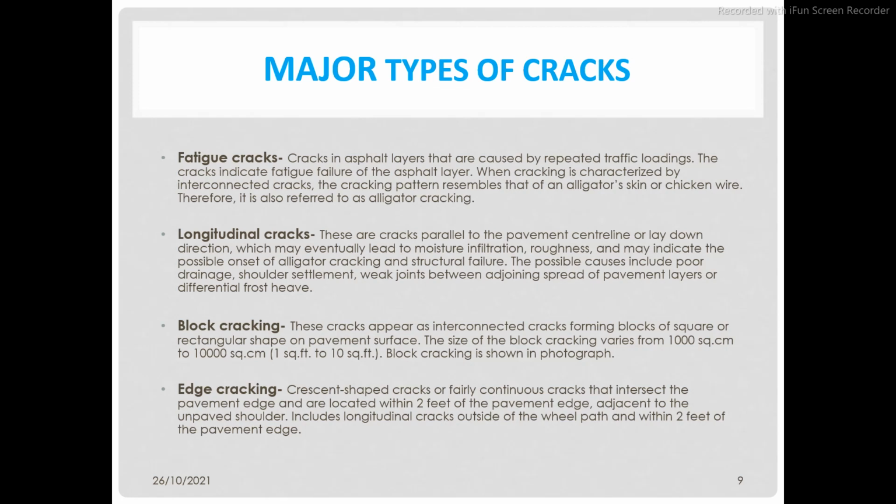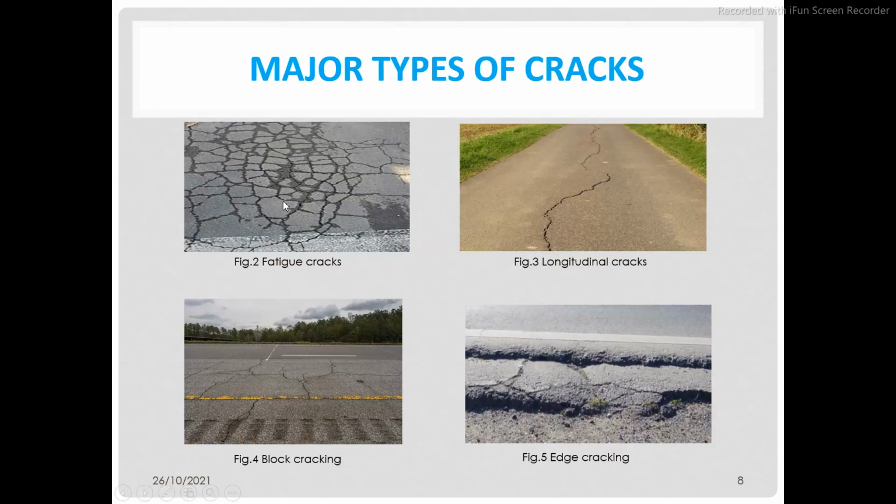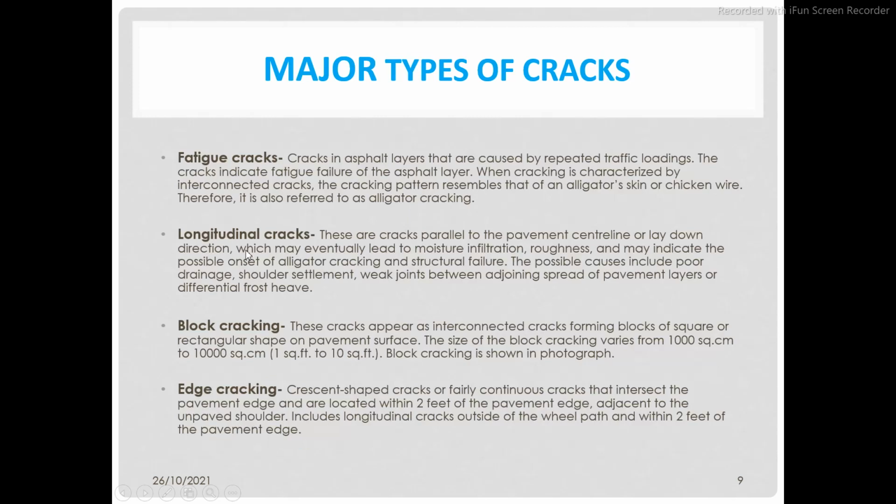Eventually, the cracks lead to a disintegration of the surface, as shown in the figure, as you can see here. Disintegration of the surface has occurred here. The final result of fatigue cracking is potholes. Alligator cracking is usually associated with base or drainage problems. The second one we have is called longitudinal cracks.